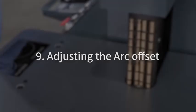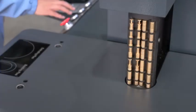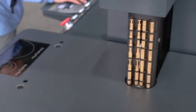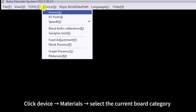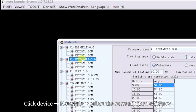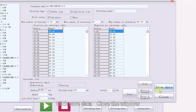9. Adjusting the arc offset. Send the material out almost flush with the bending position. Click Device, Materials. Select the current board category. Change the minimum radius of extrusion to 20 mm. Click Save Data. Close the window.